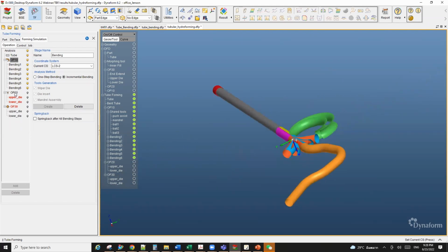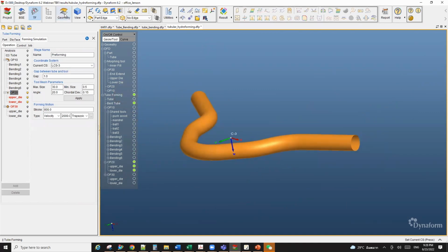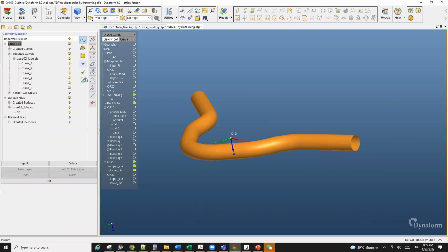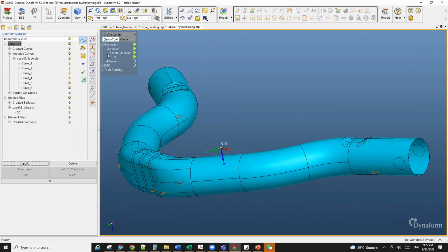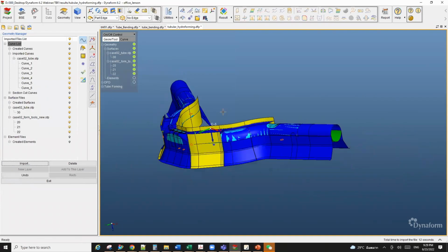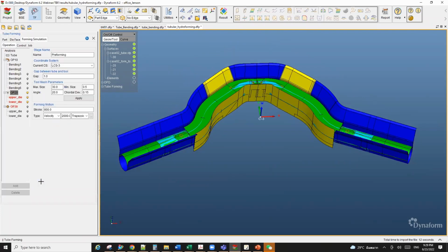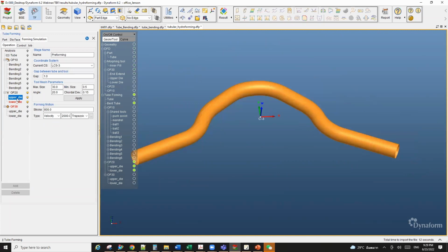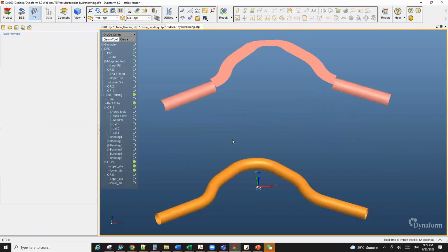Now, as for preform, we will import a geometry. We'll click geometry and then import. I have the preform geometry here. This is the one that was pre-generated. Now we're going to define the upper die for the preform. I'm going to click on define and pick upper die, select include, and then click exit.